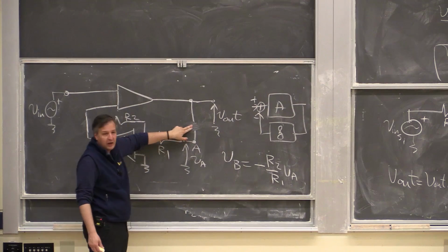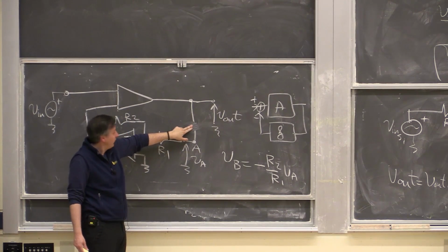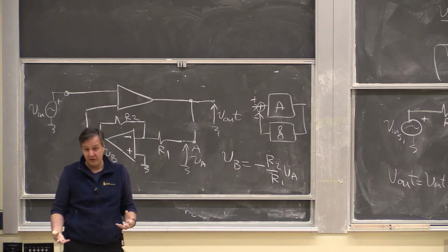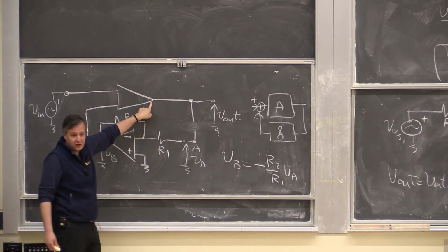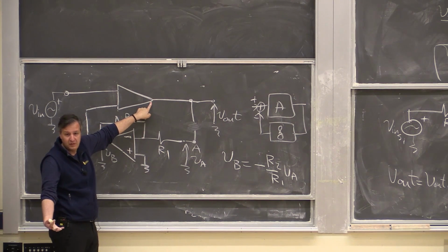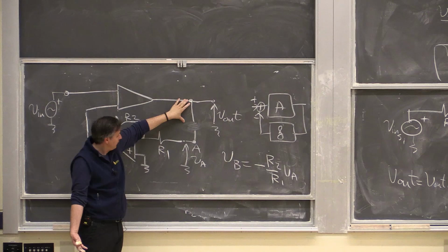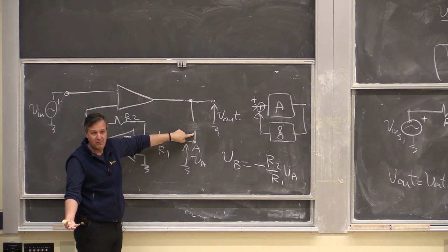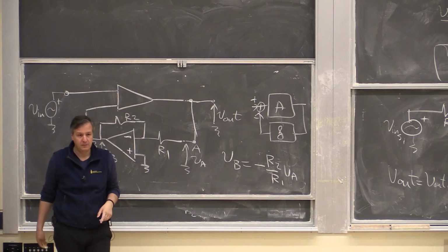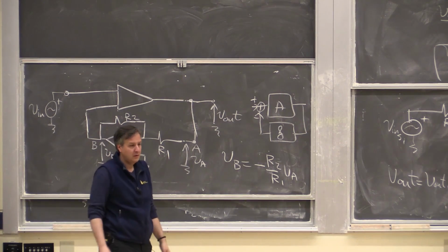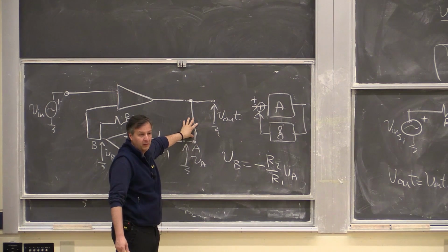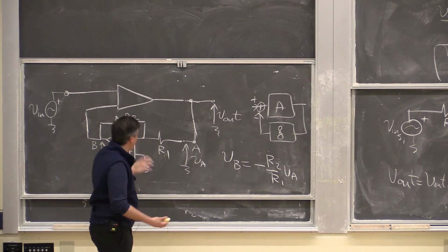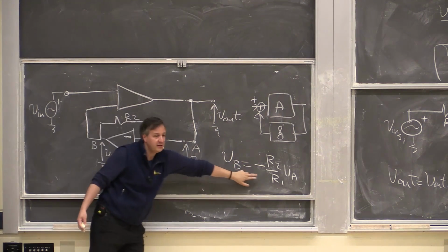Okay. Here, I need to be a little bit more careful, right? And look what is actually driving this node VA. If it was a V Thevenin with R Thevenin, I'd be in trouble, okay? I would need to put this buffer to isolate. But if we look, this is actually an op-amp, so it is an ideal source. So whatever V out it's trying to drive, when I hook it up here, that V out will stay, right? So I can make this connection. Yes? What happens if it's not isolated, like there's an external current? Then we would need to go back and isolate, right? Put a buffer there, or take into account this drop. But then I would not be able to just say, hey, this block has just this transfer function, right?